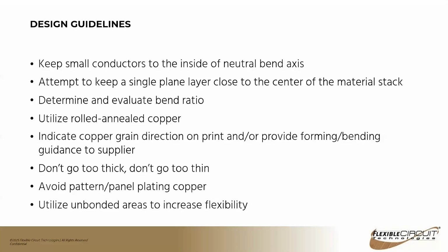Don't go too thick, don't go too thin. We've had the most success with 1/2 ounce and 1 ounce for dynamically bending or static formed circuits. We have seen fractures on 1/4, 1/3 ounce, a little bit more, or that of 2 ounce or more. It seems like the sweet spot for dynamically bending or tight bend radius is 1/2 ounce to 1 ounce.